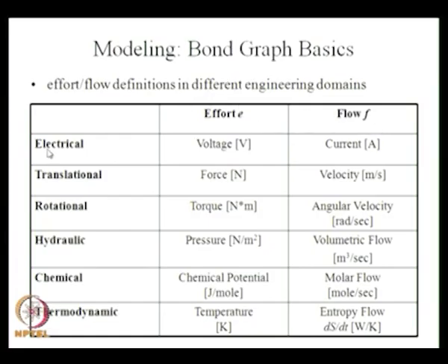For example, for electrical, effort is voltage and flow is current. For translational motion, force and velocity. Rotational motion, torque and angular velocity. Hydraulics is pressure and then volumetric flow. Chemical is chemical potential and molar flow. Thermodynamic is temperature and entropy flow.